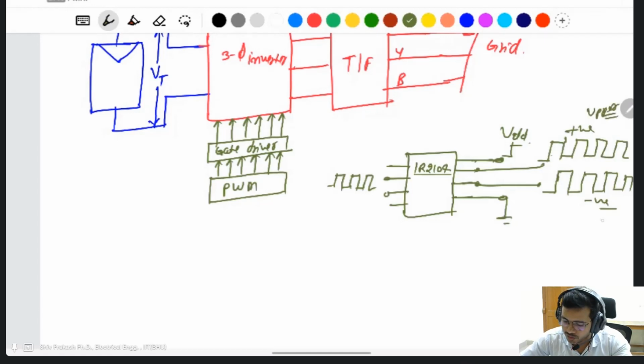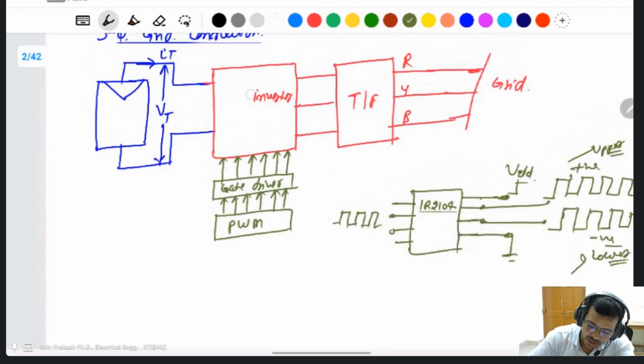This is for the lower, high side or low side. So the high side driver, this is the low side driver. You can control by only one given pulse because of the inverter, the 3-phase inverter. I have 6 switches and 2 work in complementary, like that.